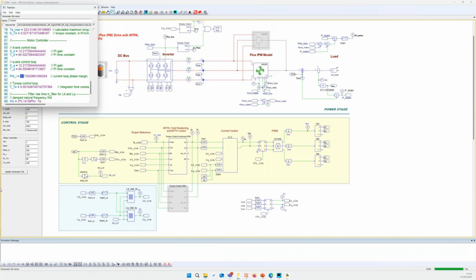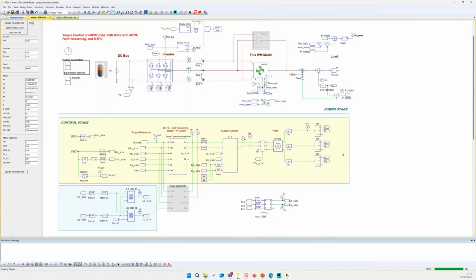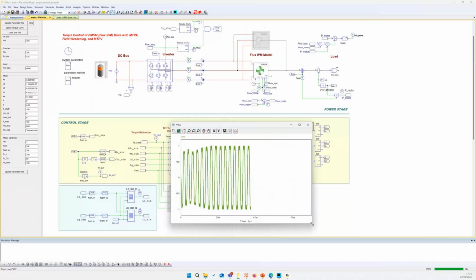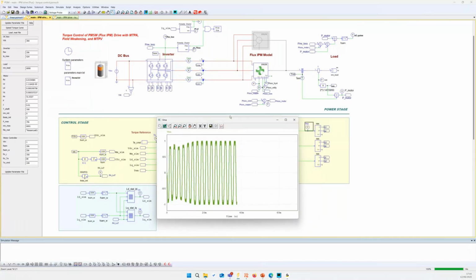But you may notice that whenever you change this crossover I term, the KD and KQ, basically the PI gain parameters, will change along with the phase margin, and you should always check that along with the modulation. The modulation is another important thing. Please remember that if you don't get expected results, the first thing you should do, and it's the first thing I do when I receive customer cases, is look at the modulation signal. We want this modulation to be within the limits of the carrier.